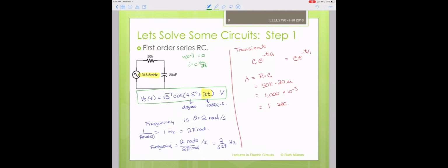The current is running through, the electrons are going from one plate to the other, and they settle down in order to build a charge that matches what's needed by the rest of the circuit. So, if you're building a charge on this capacitor, not only is the voltage during time 0 equal to 0, but the voltage immediately after you turn on the source still has to be 0 because it can only change slowly. That doesn't mean slowly in time, it just means that it can't change instantaneously.